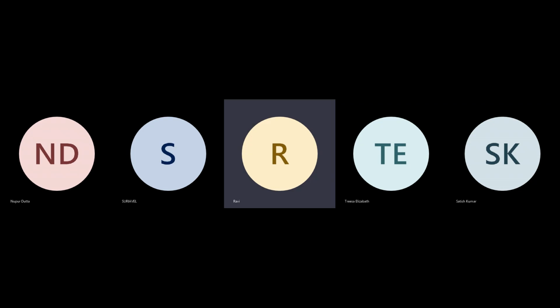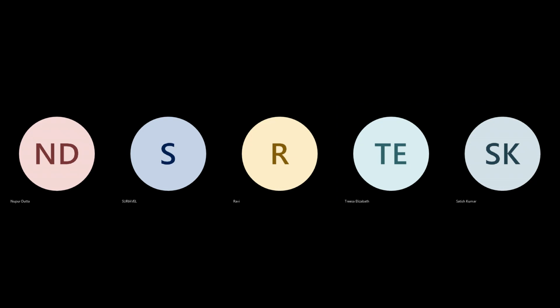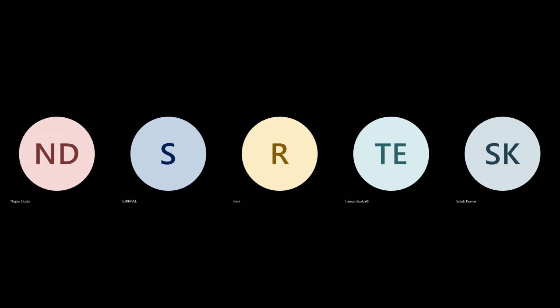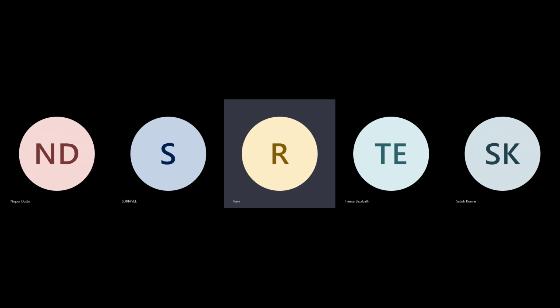And then work on what you have to do for post placement, whether you need timing optimization or you can do it only at the later stage for you to converge. These are important things you have to do. You can break it down into different pieces or run it at a single place_opt with different options. Place_opt you can run 3-4 times. Initially you may get something that is not meeting, so then you enable the timing-driven option, and it will run another iteration.